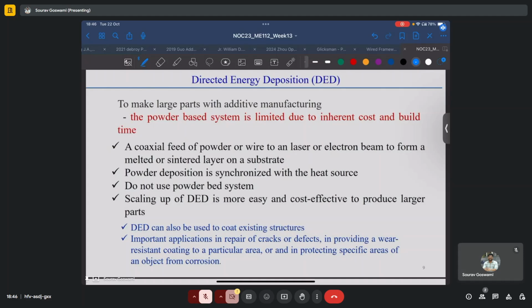Of course, some of the powder will be wasted, and typically such waste can be calculated via the catchment efficiency, which is how much powder actually got deposited into building the bead as a ratio of the powder that is originally flowing from the powder nozzle.